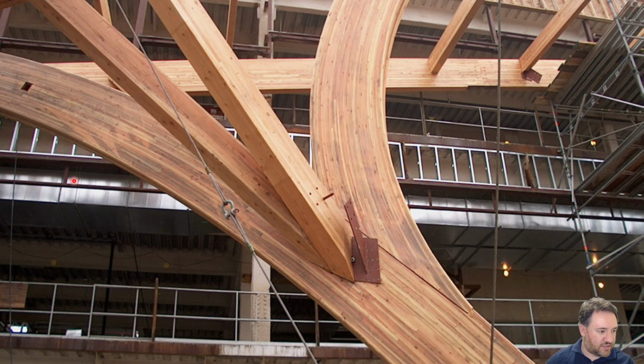Here's another picture from the same building, which has these lovely trees. I think this is maybe in Mississauga. And you can actually see a dowel or drift pin here. The steel connection here is attached to the side of this with nails, and then the piece that's going to go on here that's not there yet is going to have a slot to accept this piece of steel, and then it's going to be held in place with bolts or dowels.